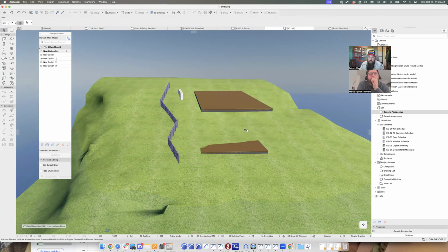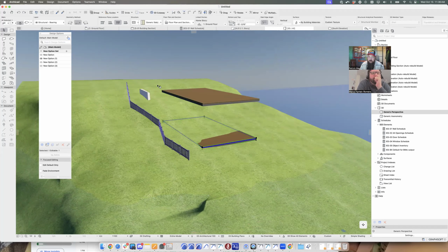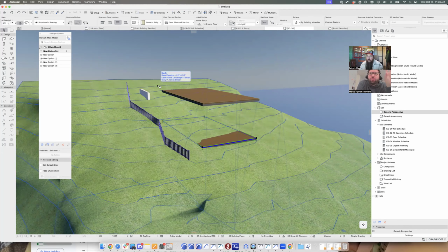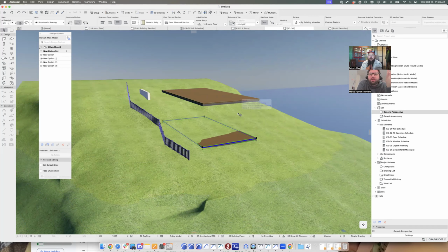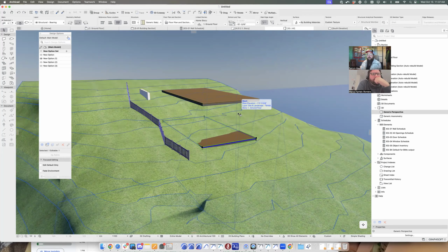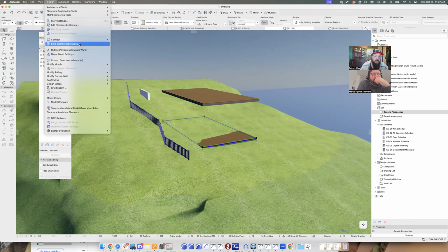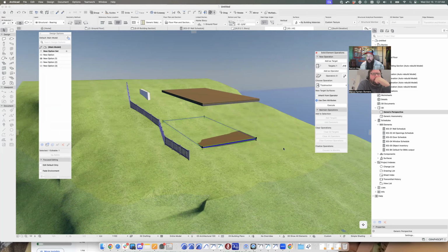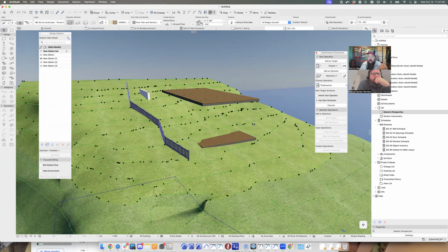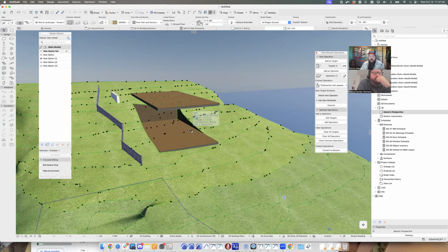How is it so smart that it just does the upward extrusion without an actual form there? So the operator is the form. It is the trimming body for the extrusion. Under design and solid element operations, I want the trimming body, the piece that I'm trimming with, to be the operator. The mesh is what needs to be trimmed, so that's going to be the target. Then the operation I'm going to do is upward extrusion, so everything above the operator gets cropped out. It's just like a roof and a wall or something like that. Yep, exactly.